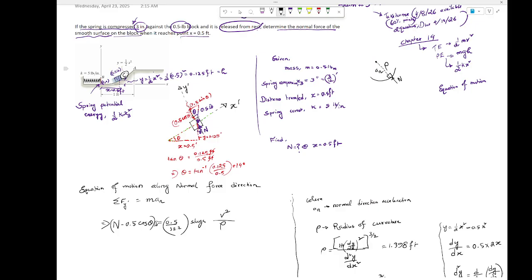At point C, because it's moving along the curve, it does have a velocity, so it has half of mv squared, that's the kinetic energy, and that is the v that you should be plugging in here. Okay, Alan? That is the v I was talking about at point C, the velocity. So you kind of get the idea. You've got to do the energy balance to find that velocity v, which you'll ultimately plug in here to find the value of what? N, the normal force.